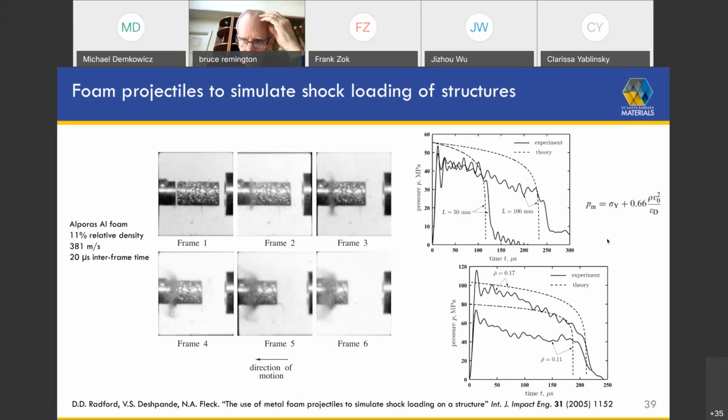Well, one of the things to do is to check for whether or not you've achieved equilibrium. So you want to calculate the forces on the front face and the back face. You want to carefully look at the strain versus time traces to see the level of oscillations in those strains.